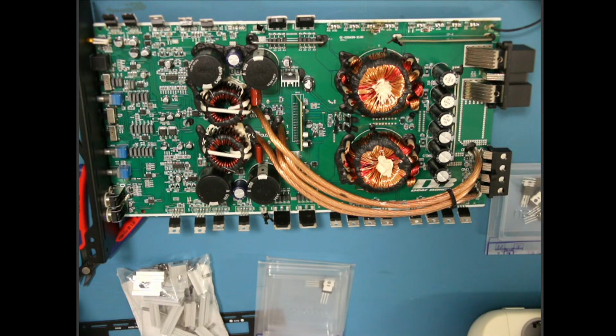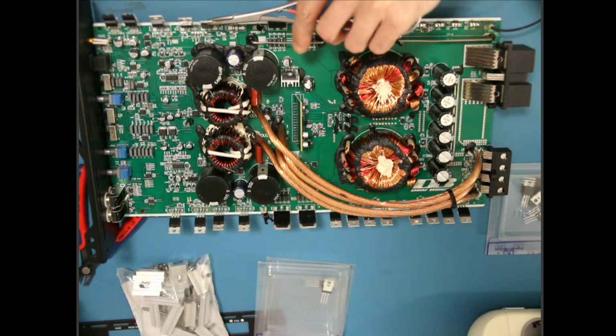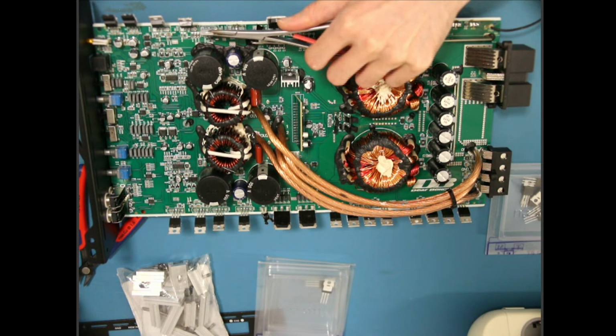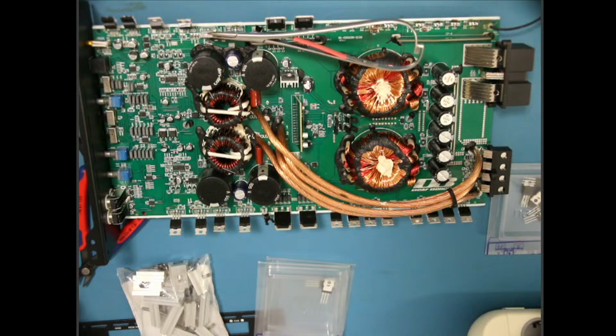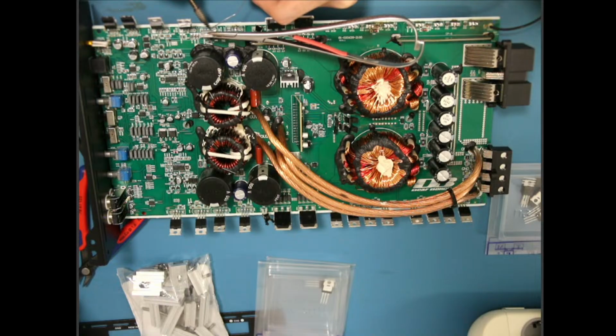Are they in parallel by any chance? Did the short go away? It did? Okay, it seems like it did. I still wouldn't be trusting this, so we'll just get it out even though it's not shorted, this MOSFET. So only a quarter of the output stage MOSFETs are shorted, meaning 1 out of 4.